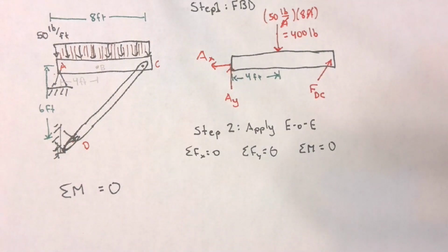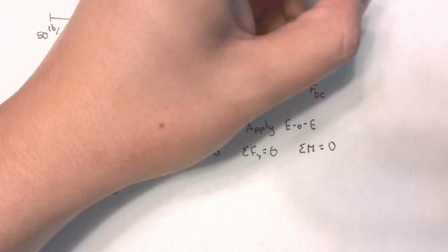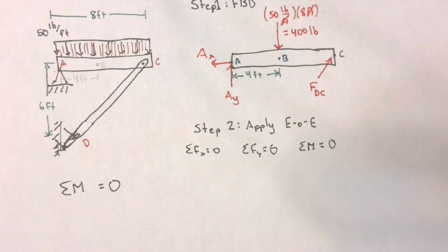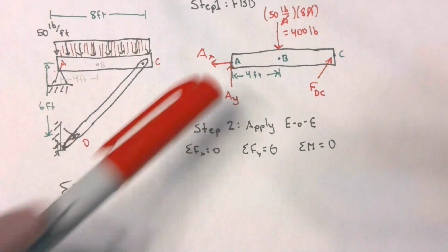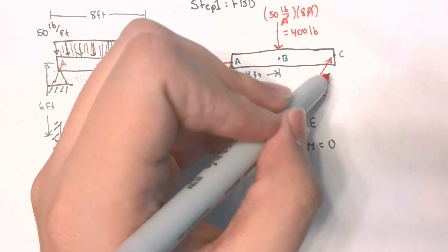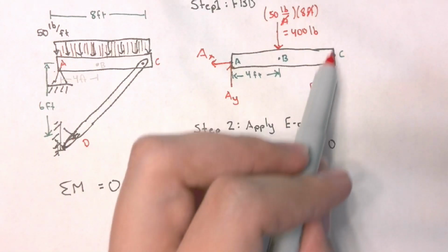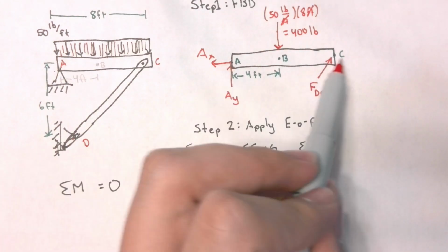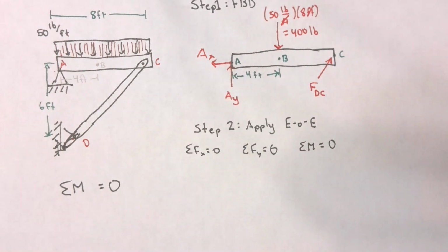I gotta label these. Point A. Okay, why A? Because then you cancel, so to speak, AY and AX. Exactly, right? So 2 unknown values. I choose point A because I cancel AY and AX. And not only that, if you look at this force, it will have a horizontal component acting right here and a vertical component. But if we're taking sum of moments here and the horizontal component is acting along the beam, we can also eliminate that from the moments, right?